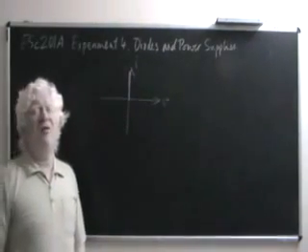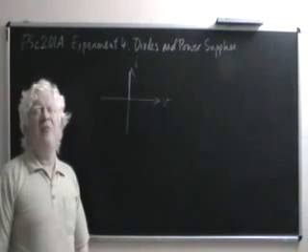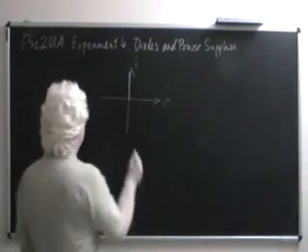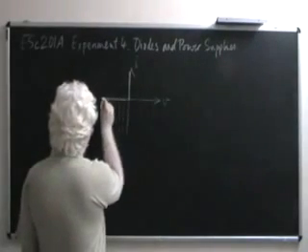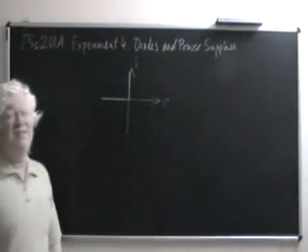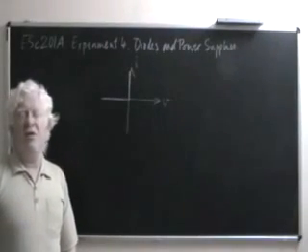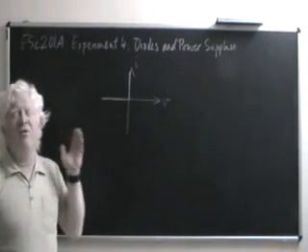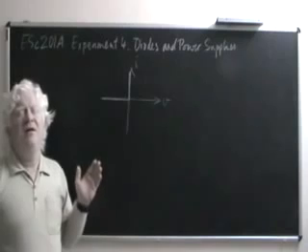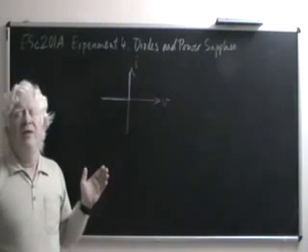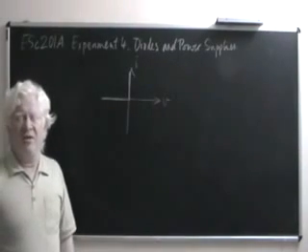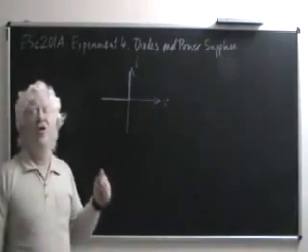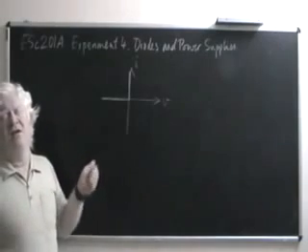And when you apply a reverse voltage, then absolutely no current flows because it acts as a very high resistance. So you would have a characteristic like this. So this is an ideal diode. No practical diode that's made with electric circuits is ever going to be ideal. But it tries to be ideal in a major part of its characteristic. Superposed on this, I will draw the characteristic of a non-ideal diode, of a practical diode.